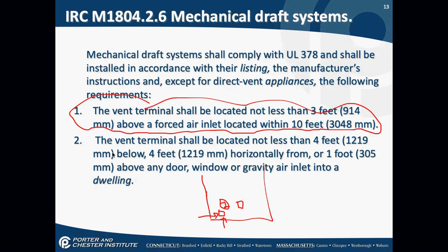Has to be located not less than 4 feet below, 4 feet horizontally, or 1 foot above any door, window, or gravity air intake.